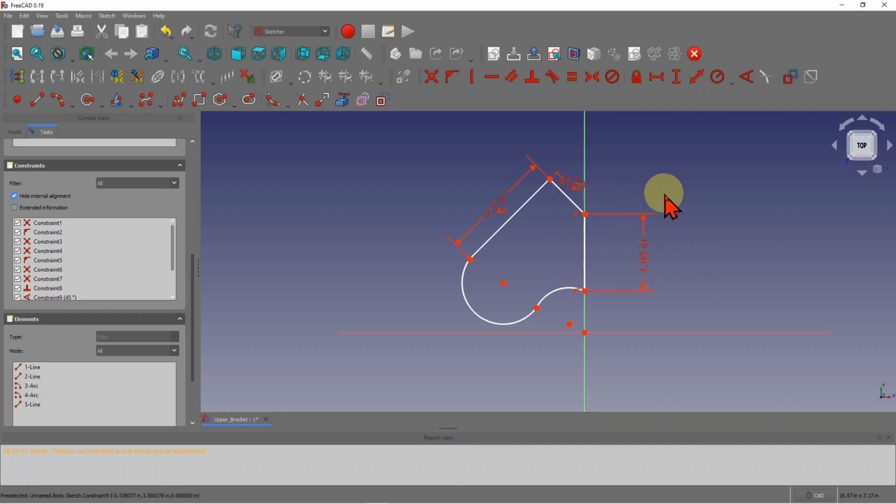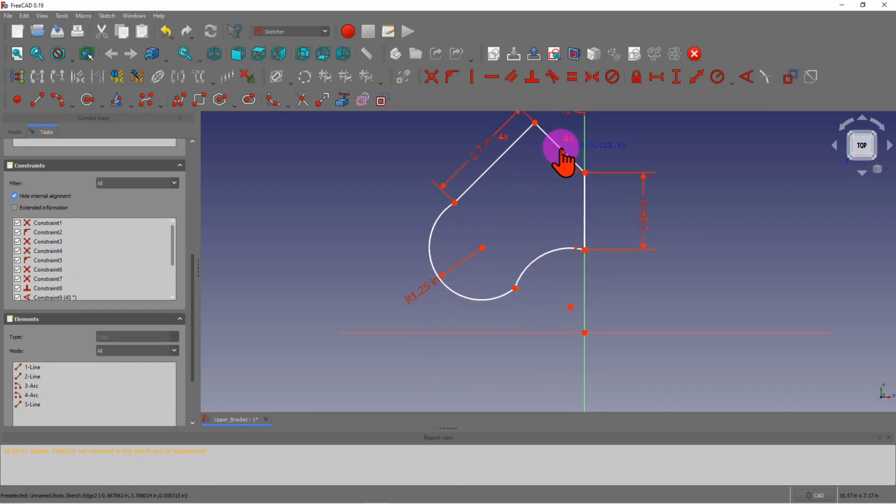Now if you go back to your tech drawing, you'll see this corresponds to that drawing. These dimensions are okay. So we are going to follow the tech drawing when we create these dimensions or the constraints. So next one is to put a radius constraint to this guy. Let's say 1.25. Now it looks like it's too big, but we're going to move this around, and still it is floating, so you can adjust it.